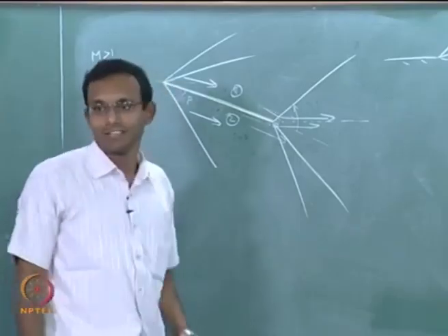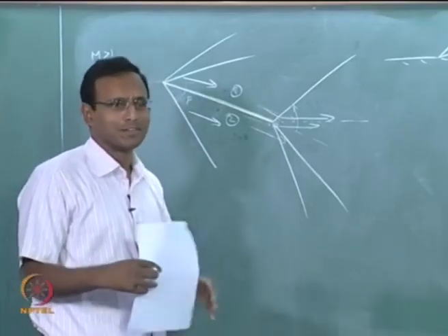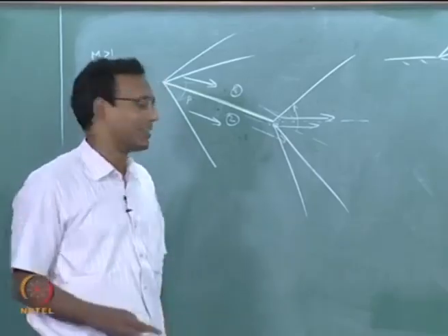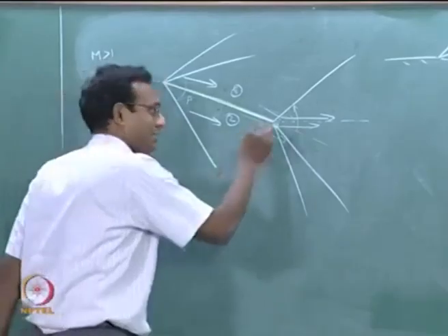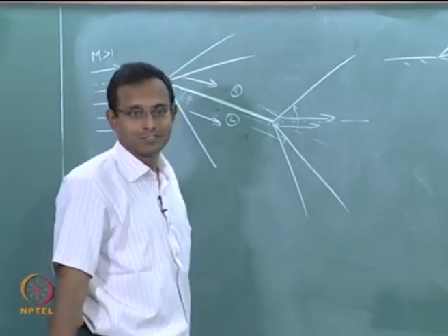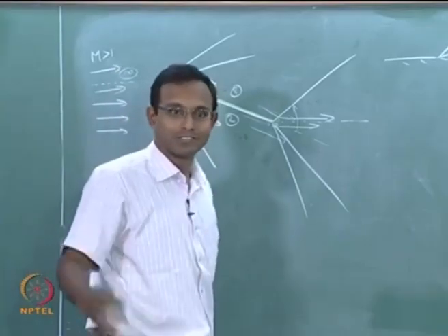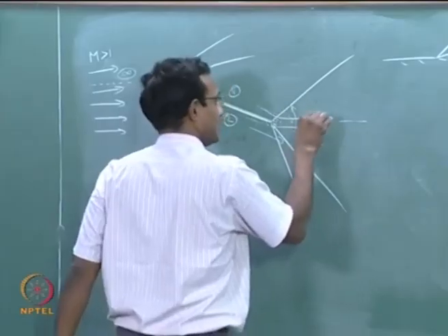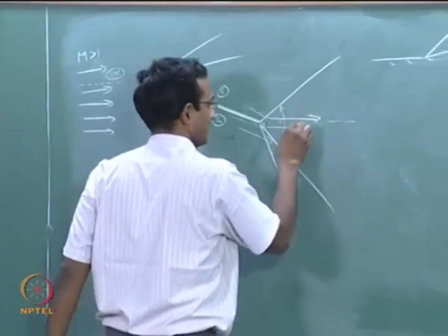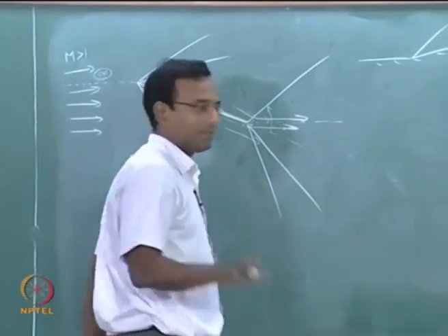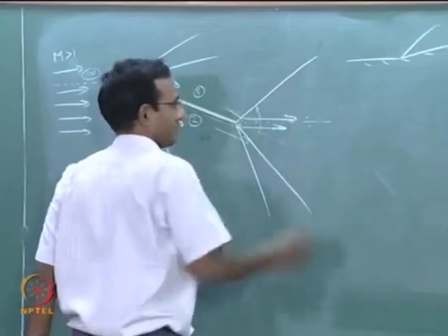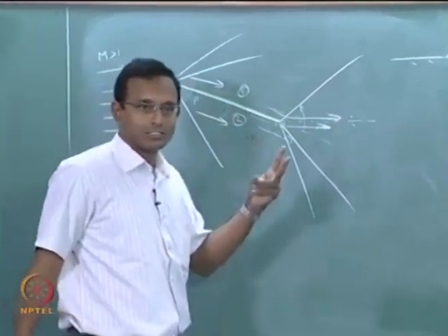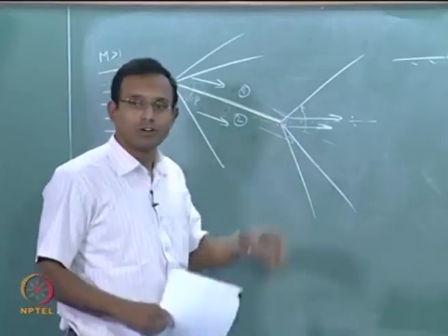There is one more condition needed. I told you already, in gas dynamics there are always two conditions. What are the two conditions? One is the velocity vector direction, the other is the pressure. We keep on repeating this all through this. Okay? We will see how it goes. We have to make sure that these two vector directions are the same, and at the same time these two pressures are the same. Two conditions, two constants I have to get.